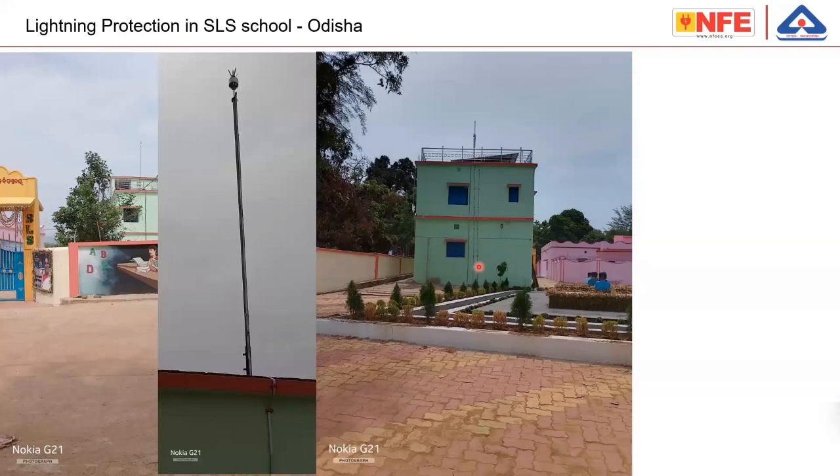You see, a very important subject of lightning protection is that down conductors must be all around the building. If you are routing all the down conductors through one side of the building, that itself is a violation of the standard. And depending upon the size of the building, you need to have multiple down conductors. It is not like the entire lightning current is flowing through one down conductor, which is again dangerous, because if you zoom this particular picture, the third line from top to bottom, also the horizontal line in the building, is nothing but